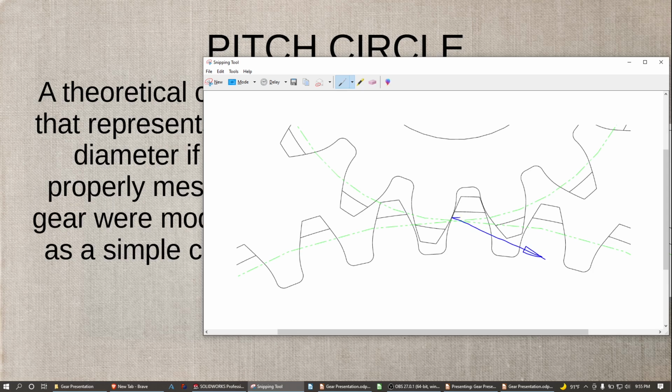And if we draw that angle off of horizontal, that's usually about 20 degrees. So the two common pressure angles are 20 degrees and I believe 14.5. I'd have to double check, but it's 14 point something. And it's very rare you'd ever get any pressure angle that's not one of those. And if in doubt, go with 20.